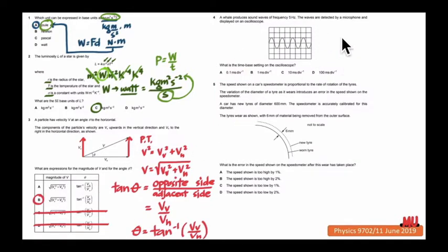Okay, now for this question, this horizontal line or axis is the time base in the oscilloscope. This time, when there is a complete oscillation, gives the period, and that period is the reciprocal of frequency. The frequency is given, and so we just plug it in, 1 over 5 Hertz. The period therefore is 0.2 s, this represented by orange line. Alright, from that, this division, which is half of that period, should be 0.1 second.